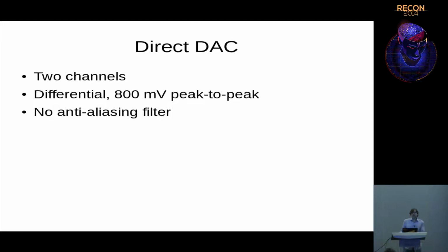What I'm trying to do here is kind of use HackRF as a general purpose test tool. At its core, HackRF is an RF signal generator and an RF signal analyzer. But it could be used for more than that. It can be used as an oscilloscope, which I just showed, or it could be used as a function generator. But again, it has similar limitations or things you have to be aware of if you're going to plug into it.